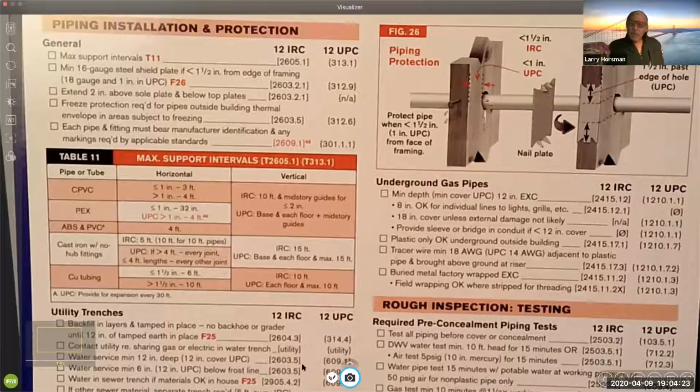So, shake your pipes loose. But your typical fixture that's produced today doesn't open and close rapidly. You have to turn and turn your faucet to get it all the way on. There's a reason for that, and that's to keep you from having water hammer issues.